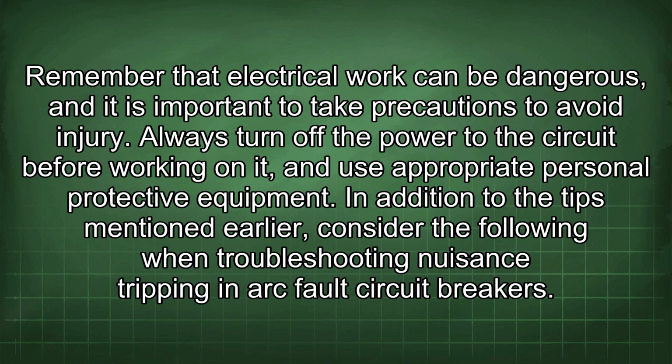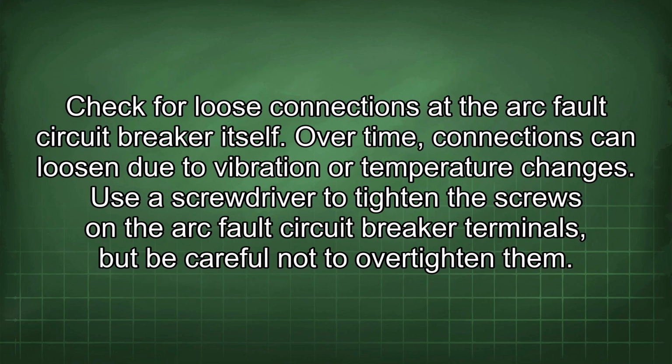In addition to the tips mentioned earlier, consider the following when troubleshooting nuisance tripping in arc fault circuit breakers. Check for loose connections at the arc fault circuit breaker itself. Over time, connections can loosen due to vibration or temperature changes. Use a screwdriver to tighten the screws in the arc fault circuit breaker terminals, but be careful not to over-tighten